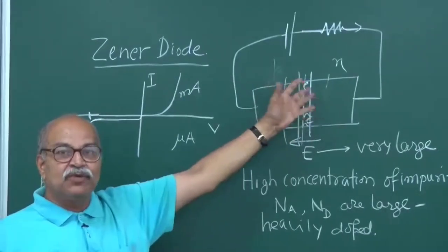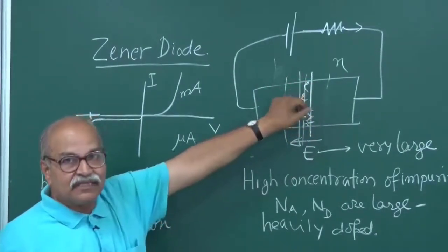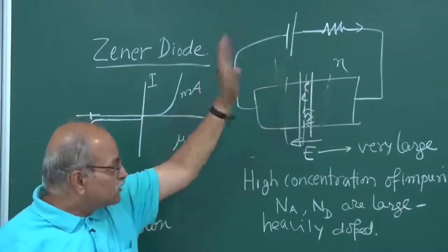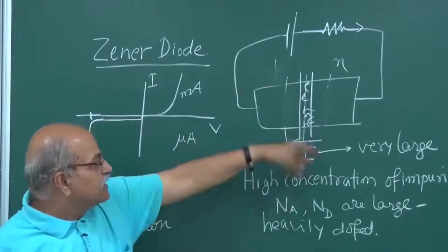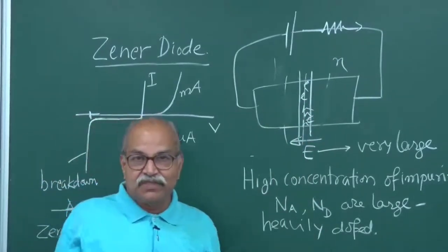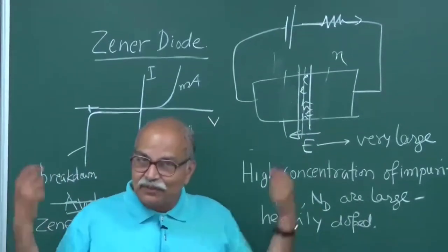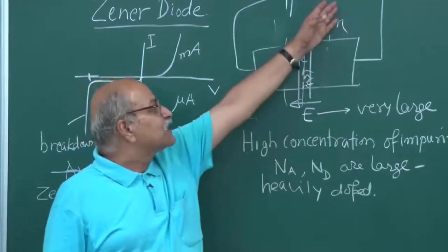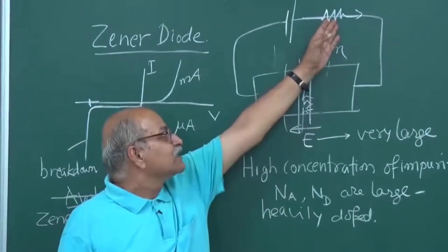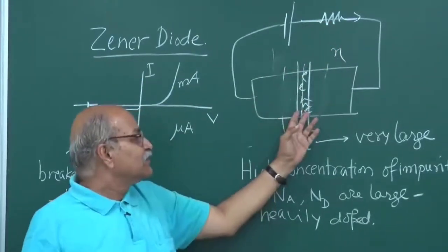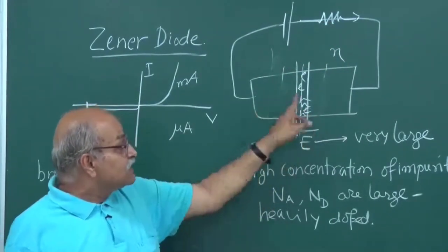The moment it becomes 2 volts, you have all this process starting, and then it cannot increase beyond 2 volts, because at 2 volts itself you try to increase and the current will increase very high, and if you put really more than that 2 volts, then the whole thing can get burnt, right? So you must put a resistor here, so that any extra voltage drops here, and here remains the voltage for which it is created.